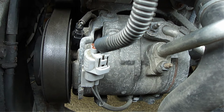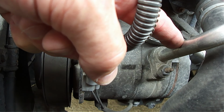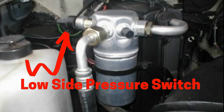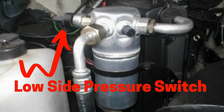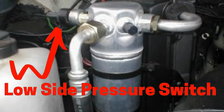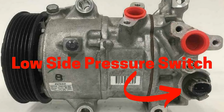The easiest way to locate the pressure switch is to follow the AC lines coming out of the compressor. The larger line will be your low side pressure switch, and the smaller line will be your high side pressure switch. The low side pressure switch will be located on the larger line between the compressor and the evaporator and is almost always on or near the accumulator, which looks like a metal can as shown in this picture. The low side pressure switch can also be located directly on the compressor as shown in this picture.